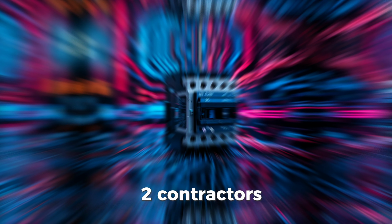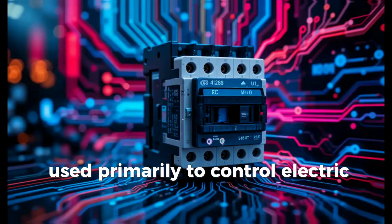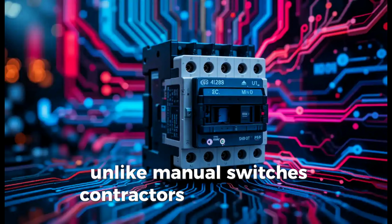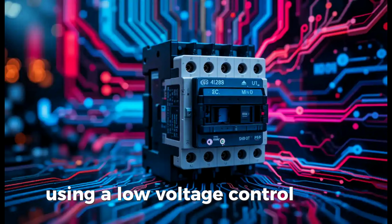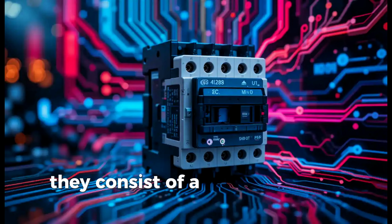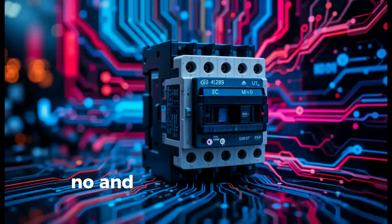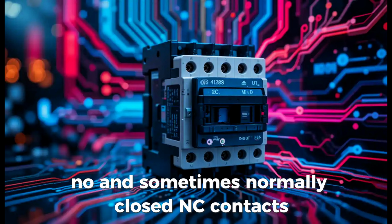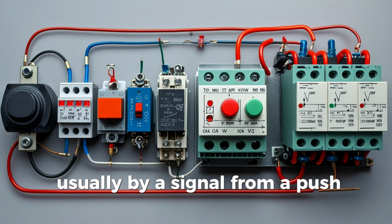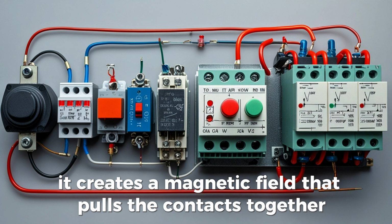2. Contactors. Contactors are electrically operated switches used primarily to control electric motors and other high-power loads. Unlike manual switches, contactors are controlled remotely using a low-voltage control circuit, making them ideal for automation and safety. They consist of a control coil and a set of electrical contacts, typically including normally open (NO) and sometimes normally closed (NC) contacts. When the control coil is energized, usually by a signal from a push button, relay, or control circuit, it creates a magnetic field that pulls the contacts together.